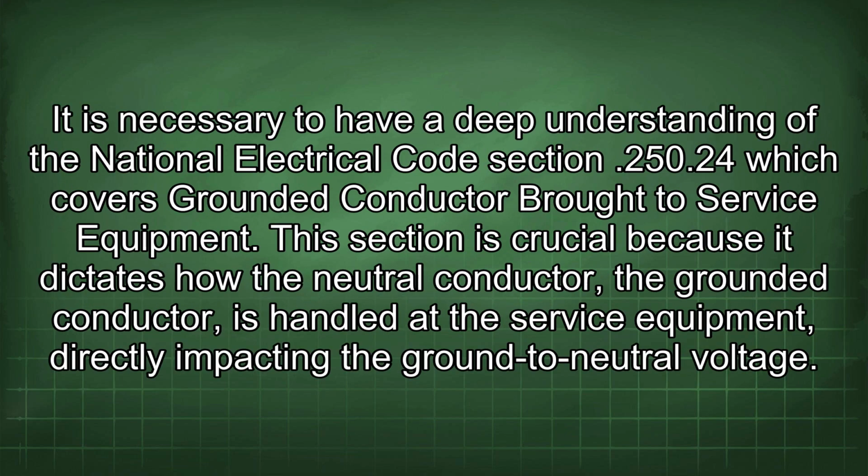It is necessary to have a deep understanding of the National Electrical Code Section 250.24, which covers grounded conductor brought to service equipment. This section is crucial because it dictates how the neutral conductor, the grounded conductor, is handled at the service equipment, directly impacting the ground to neutral voltage.